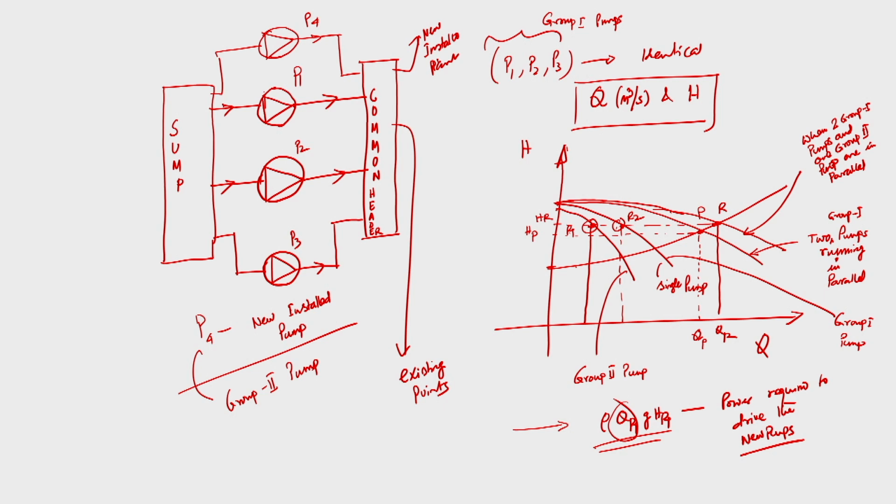Water is now conveyed from a common header to different routes, to different branch lines. I do not know which one has the least resistance in the system, but it is obvious that whenever pumps are connected in parallel, they will run if and only if all of them experience the same system resistance. It is also true that they will always try to follow the minimum system resistance.